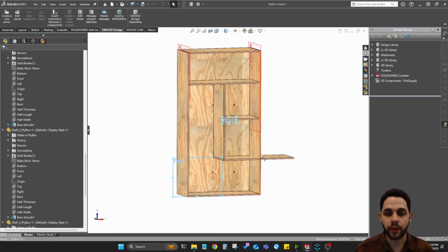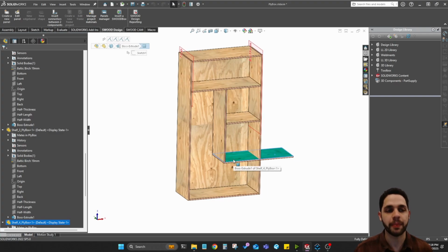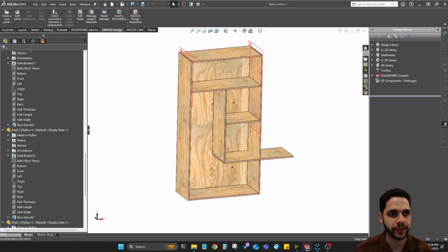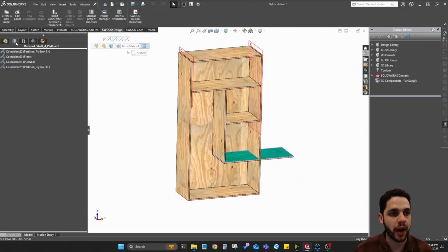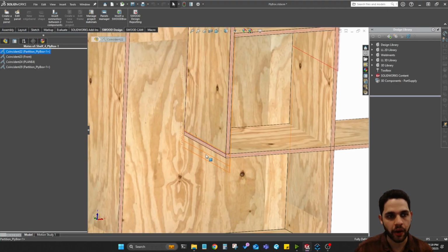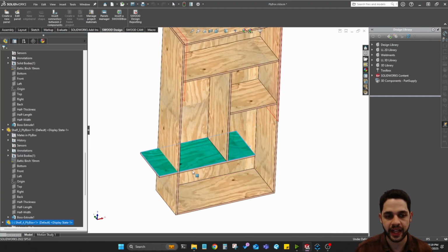The reason why my panel is sticking out the side of the frame has to do with the mate relationships between this panel and the midplane. And to check that, I'll go ahead and click on this panel. I'll go to Property Manager, and I'm looking for that relationship that's causing the panel to grow out the side. So I'm looking through, and I find this one here. So okay, I know that I need to suppress this relationship, and when I do that, now this panel is floating free in that degree.